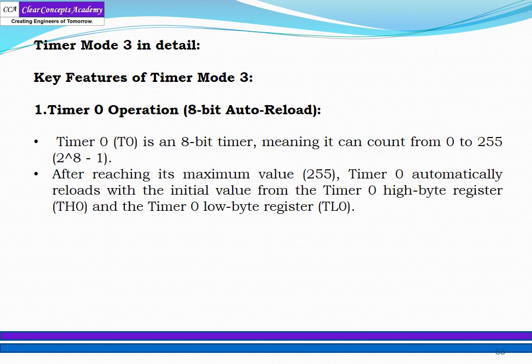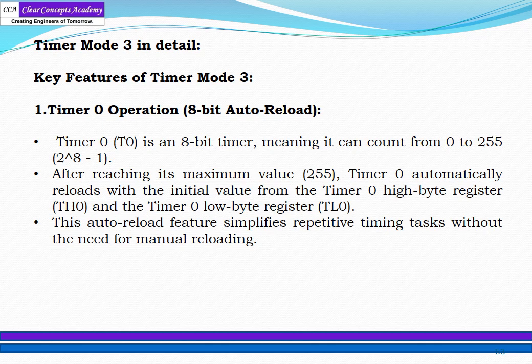After reaching its maximum value of 255, timer 0 automatically reloads with the initial value from the timer 0 high byte register TH0 and the timer 0 low byte register TL0. This auto reload feature simplifies repetitive timing tasks without the need for manual reloading. This is auto reload mode, which we have already discussed in an earlier discussion.